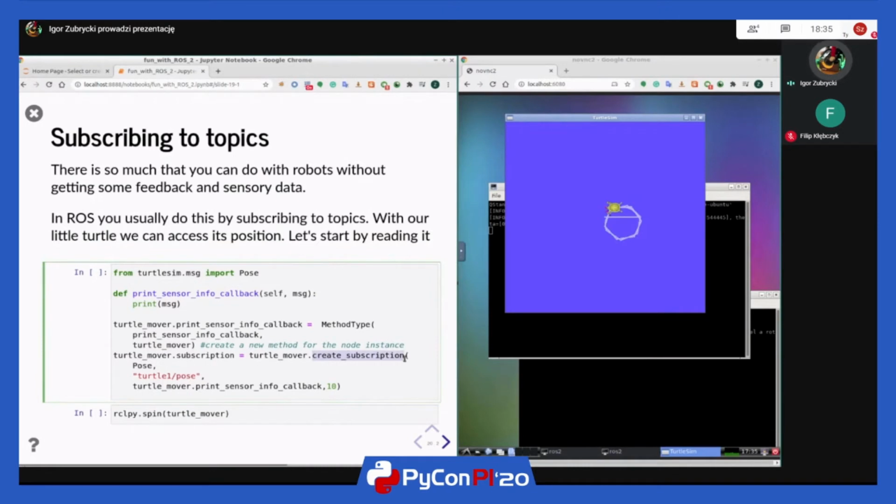So we are a subscriber to a particular topic. This topic is called turtle1 pose. Every couple of milliseconds, the robot is sending its own pose, and we will be reacting to this. So first we create the subscription, and in the subscription we are saying, if there is a new message on the topic, please run this function.